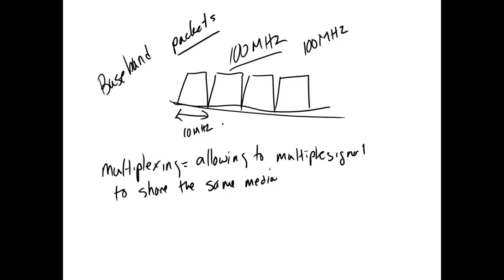So are we saying that baseband and broadband both are multiplexing? Yes, they're both multiplexing, but one of them, in digital, you'll learn it as time domain multiplexing, which means the device does not have to be modulated. We just put the digital data out there.